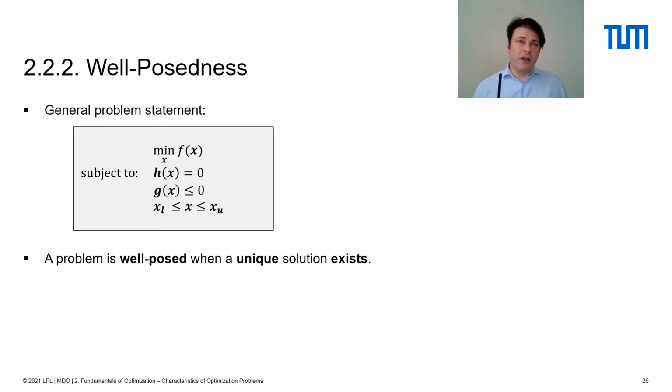That produced a scenario where, upon increasing your cross-sectional area even further, you would minimize your objective function even further, without any boundary. And in a mathematically sloppy way, you could say the optimum is at infinity, but since that is not a proper location or a valid specification of a design, this counts as there is no solution.